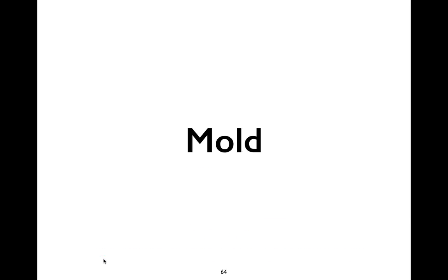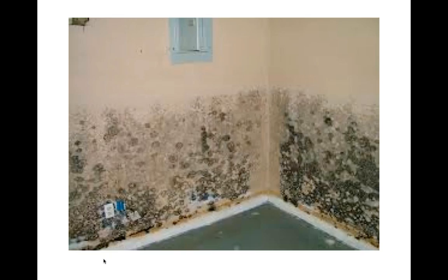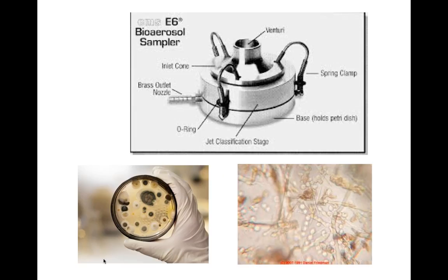Another thing that we wind up examining in indoor air quality is mold. Mold, of course, is an enormous issue now because a lot of people are attributing, rightly or wrongly, there's a lot of research that remains to be done, a lot of indoor air quality issues to mold. This is a really extreme issue that this could have been flooding from Sandy or from Katrina. You know, building materials are affected. The paint, the paper on wallboard are all materials that mold will grow on and consume, will eat. If you leave an area that has these kinds of materials unprotected and wet for long enough, you can start to grow mold. And this is a really extreme case of that.